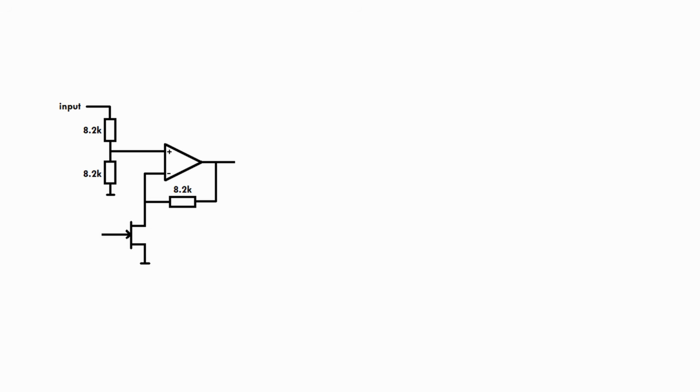So we need to add more components, starting with this. What this is essentially is an amplitude detector, right? So it's a diode and a capacitor and a couple of resistors to control the time constant of this thing, which we'll talk about later on as well. But basically we're going to get a DC voltage on this capacitor, which is proportional to the amplitude of our signal. So the bigger the amplitude of our signal becomes, the bigger the DC voltage on this capacitor. It's as simple as that. We're just converting the amplitude of our signal into a DC voltage that we can work with.